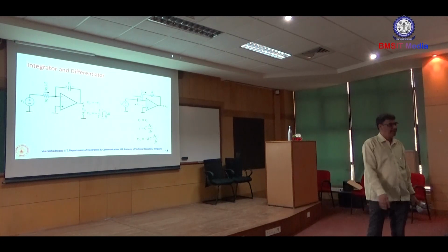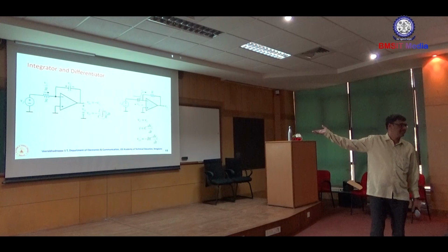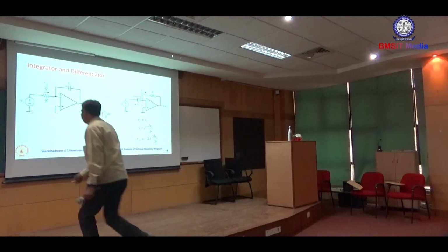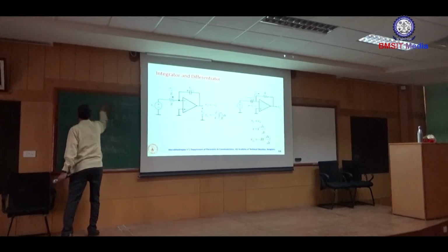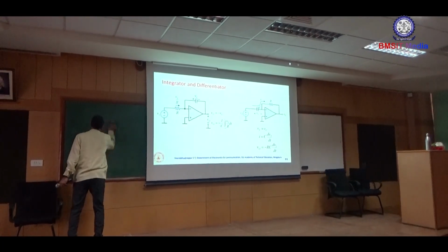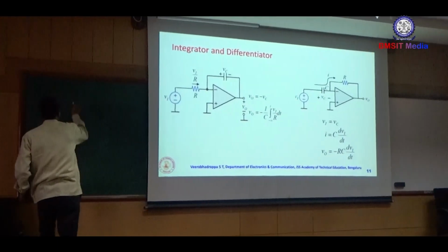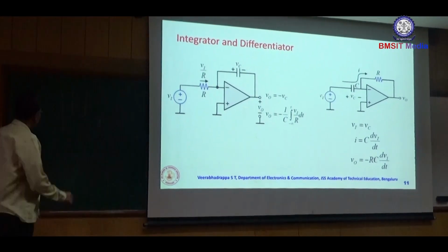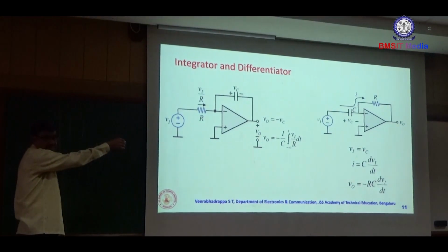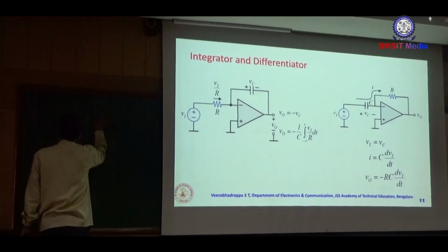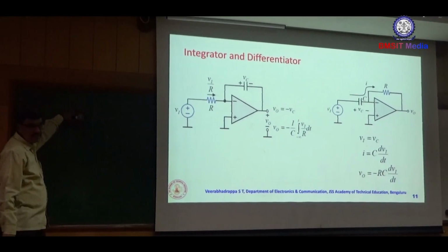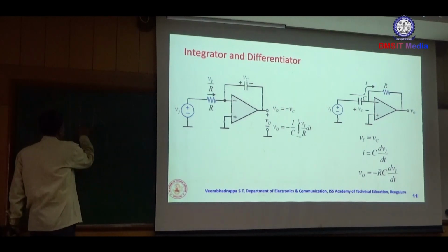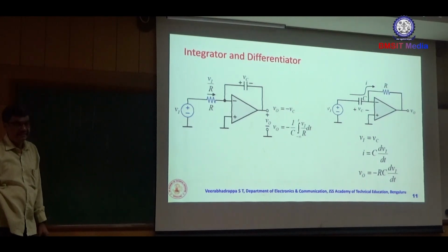When applying a square wave, you are going to get a triangle, because the integral of a constant is t. T by RC, that gain you have to consider. Means if you are applying a square wave to the input signal, then your output is, because of the inversion, a negative sign, minus 1 by RC gain, and then decreases. Until that plus gain, that output is decreasing. When that output maintains the level of minus, then minus of minus becomes plus, then that capacitor starts, that means that signal starts increasing.